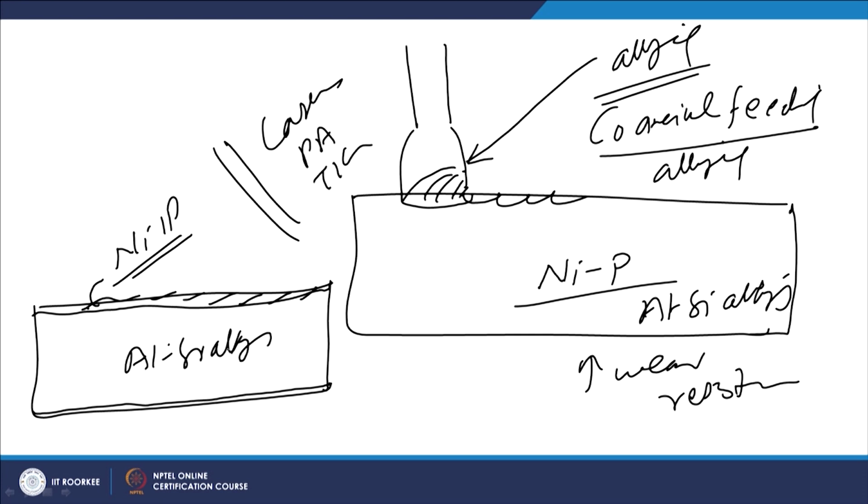Now, I will summarize this presentation. In this presentation, basically I have talked about the melting or fusion based approach for modifying the surface composition, and any high energy density heat source can be used for laser alloying, wherein at the surface we apply the required element to be introduced, and then it is fused with the substrate using a suitable heat source, so that the surface layer composition can be modified. However, we have to keep control over the dilution level during the melting of the substrate.